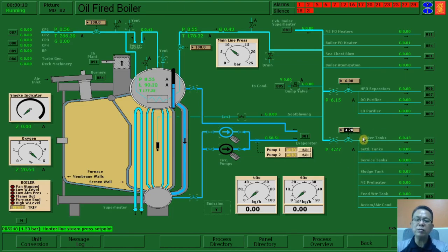So we need to open the valve quickly. Okay, opening here the drain, and opening the valve through the tanks by 50, and now we make it 75. Whatever alarms are activated in the engine room should be attended to and checked. We never neglect any alarms.